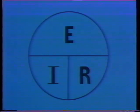Right now, we want to figure some current values, so we cover the I and we get E over R. Well, let's put in some numbers and see if it works. The light bulb in our circuit has a resistance of 6 ohms. The batteries we're using each supply 12 volts. So, to find out how much current we should have in a circuit with one battery, we set up the formula like this. I equals E over R. So I equals 12 over 6.